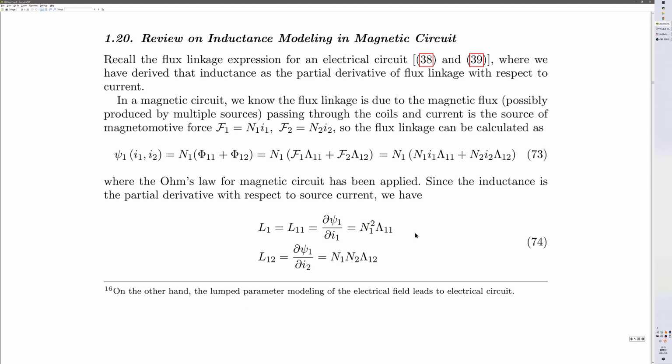However, in an electrical machine this is not generally true, because the magnetomotive force is not always equal to the turns number times the current. To be more specific, the turns number is not always constant along the air gap.